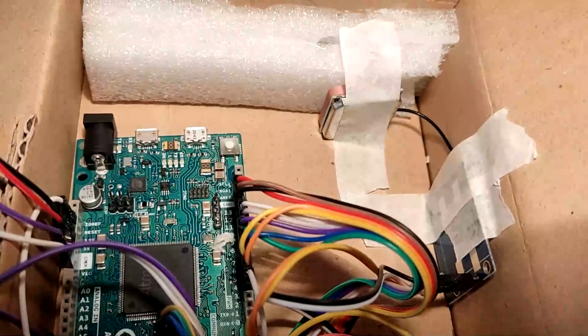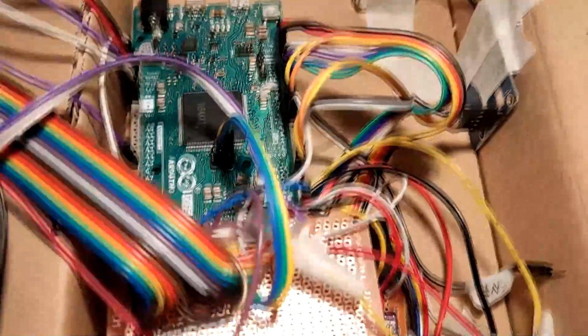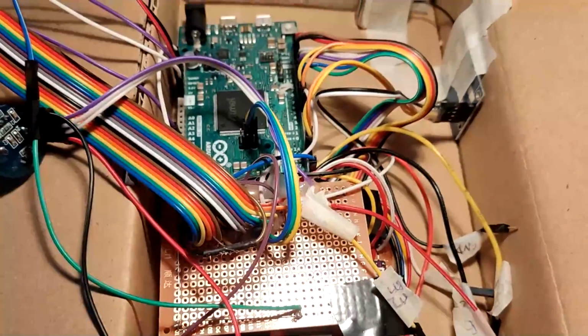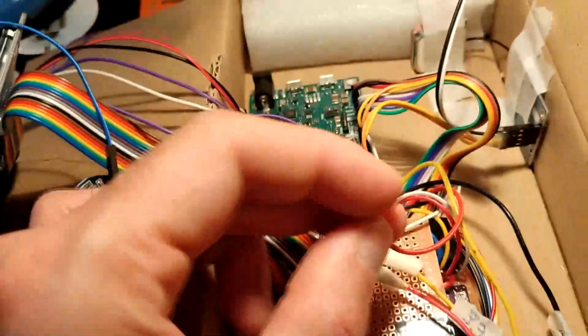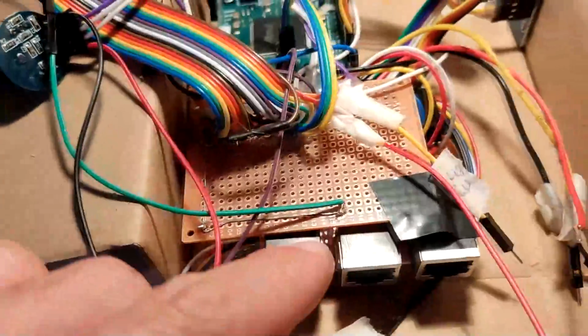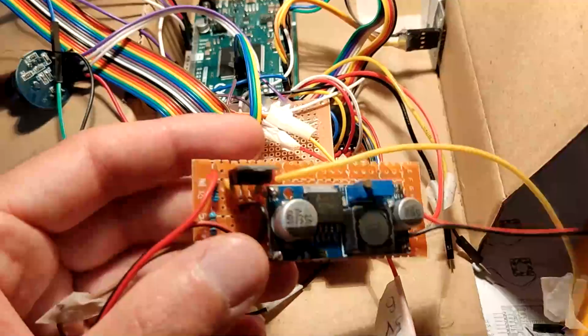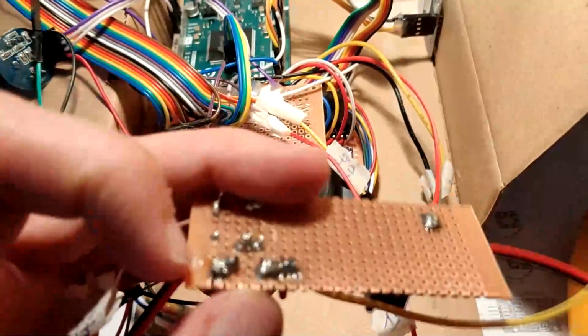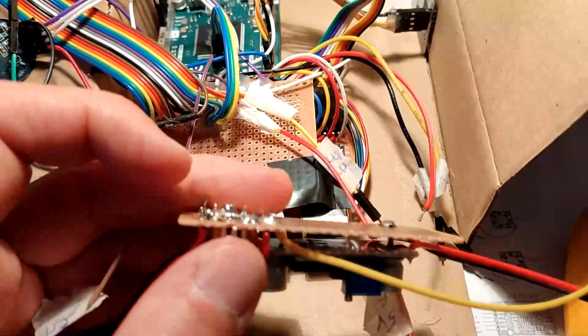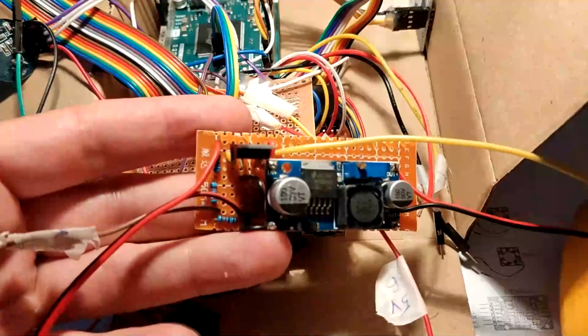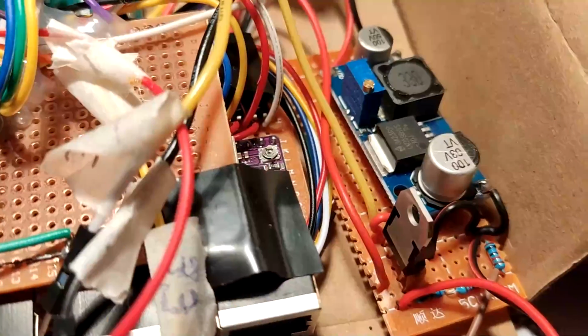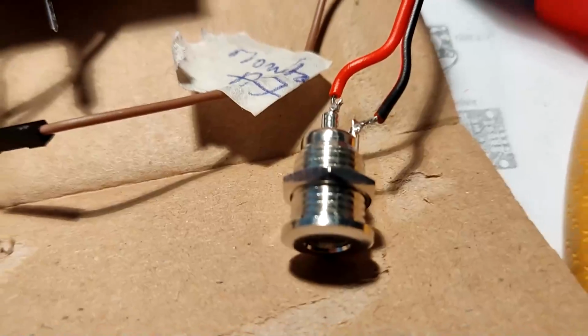Here I place the GPS module with the antenna on top, like it will be in the future box. I have the red wire here which powers the drivers below. I'm going to solder it directly on the input, and the 12 volts on the red wire here. So it's going to supply the VMOT of the drivers with the 12 volts of the battery. You can see now it's done. The red wire is directly connected to the input.